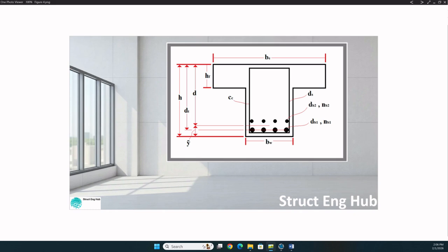Positive moment means that the rebars will be placed in the web and the compression zone will be located at the top of the cross-section. The compression zone can be rectangular in shape when entirely located within the flange, and thus the flange section can be treated as a rectangular section with constant width equal to B effective. If the Whitney equivalent depth of the compression zone exceeds the thickness of the flange, the compression zone will have a T or L shape and the cross-section will require a different set of equations to calculate the design strength from those used for a rectangular section.